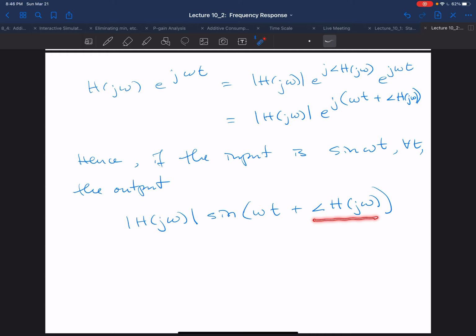So it's very easy to characterize the response of an LTI system to a two-sided sinusoid like this. It's important that the output is at the same frequency. If you feed a sinusoid into a nonlinear system, in general you will get a component of the output that is a sinusoid at the same frequency ω, but you will generally also generate harmonics.